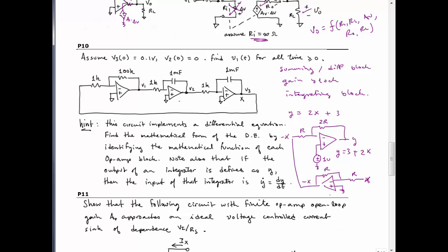Now when I feed minus X into the second op-amp, I will in fact get my Y equals 3 plus 2X. So that's not to do with this problem directly, but it's just to give you a little picture of how you can implement an arithmetic expression, an algebraic expression, using some op-amps. And what we've seen here is summing, difference, scaling. Okay, well, to implement a differential equation, you have to have a derivative in there.